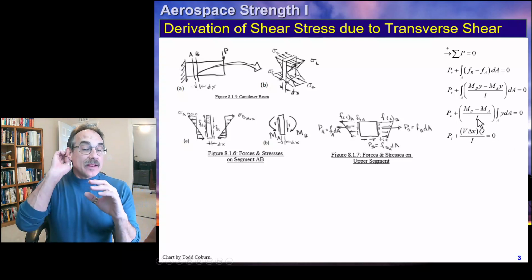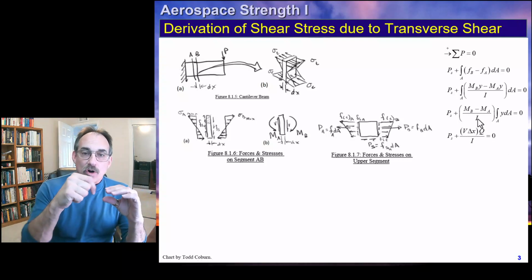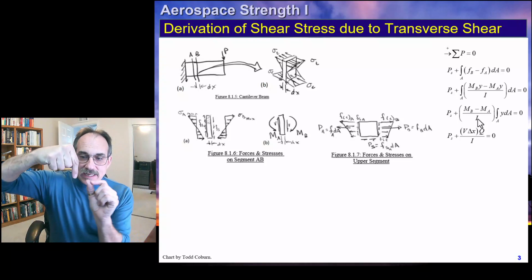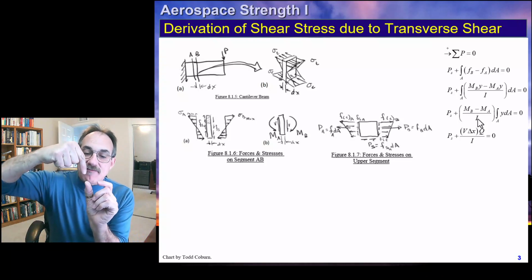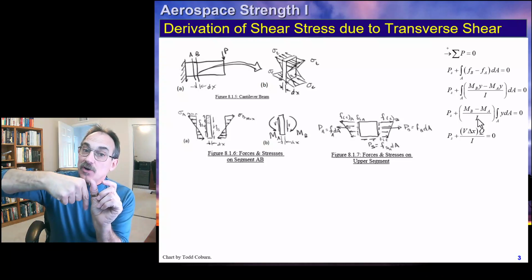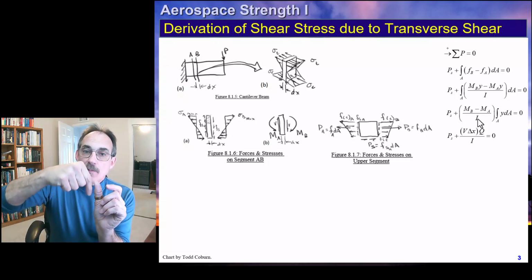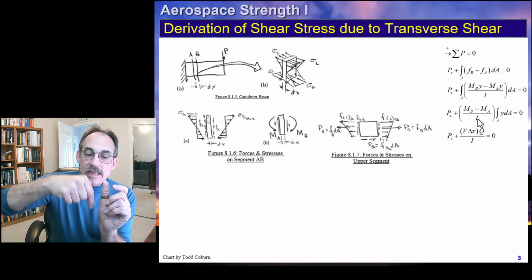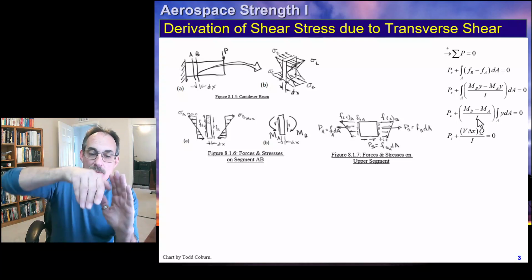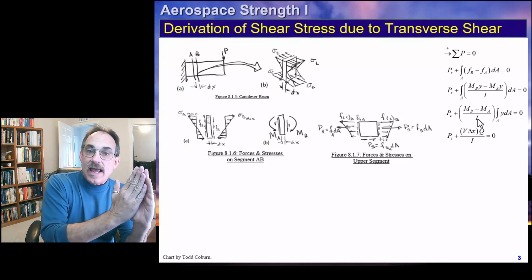Now remember, if we have a force acting and we multiply it by 1 inch, that V, internal shear, whenever we have internal shear, we're changing the moment in the beam. So if the shear is acting downward, it's going to be adding moment as we move away.